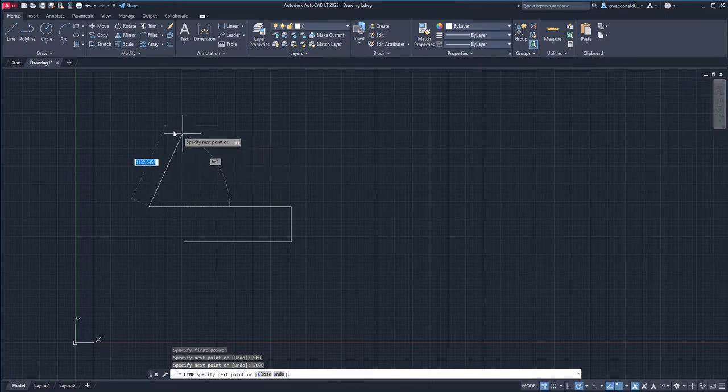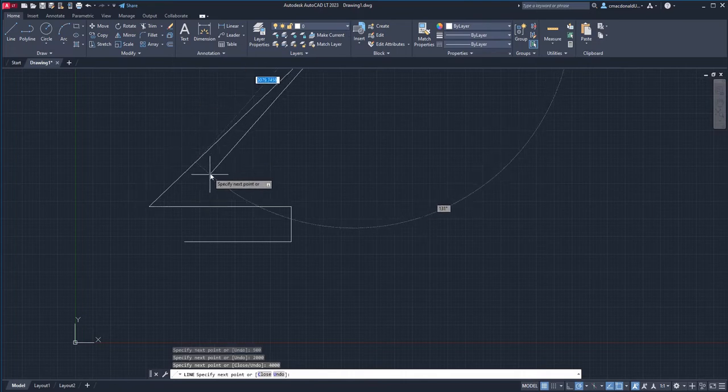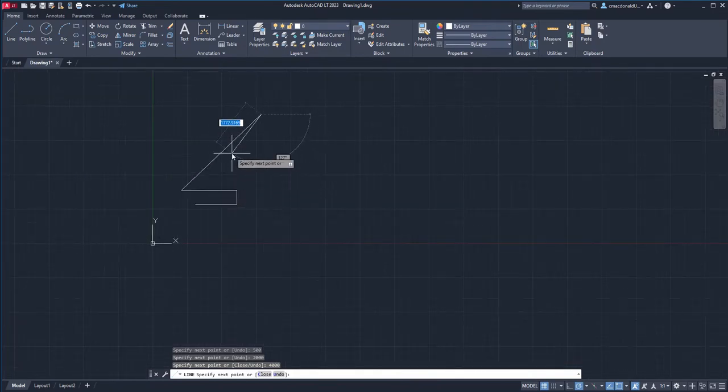Like let's say I want to move in this direction anywhere up here, and I've got this cursor sort of in this direction, and I'll try typing 4000, so you guys can see just how far this can extend, and I hit enter. Oh, let's zoom out. Perfect. So as you can see, it stuck with the direction that I gave it, and it produced the distance that I wanted. You can also produce angled lines very easily, and I'll show you guys how that's done.